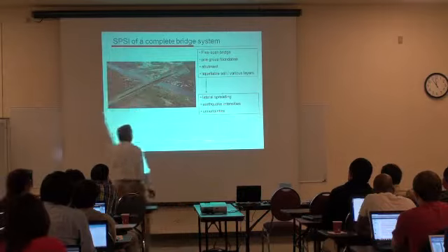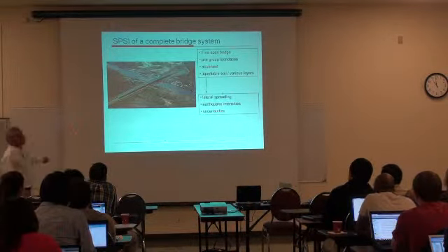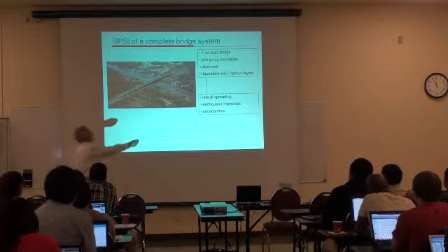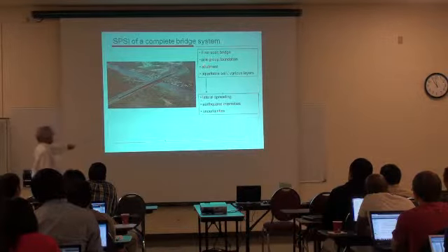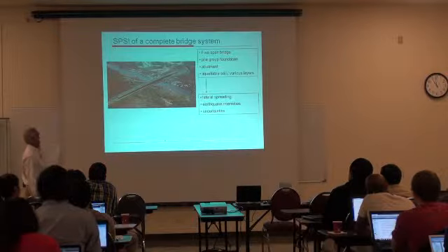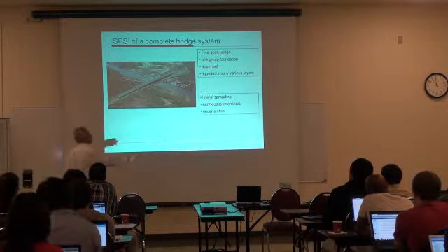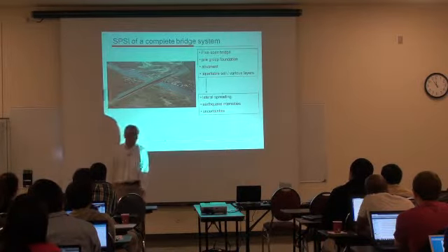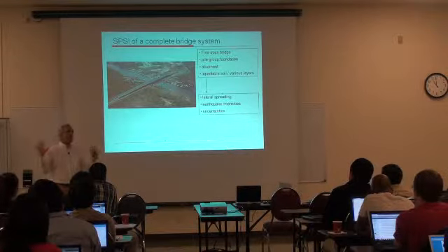This other example, I had to do a compromise. We wanted to model the whole bridge and the soil. So it was a 5-span bridge with a pile group foundation, with abutments, and with liquefiable soils with different thicknesses at different points. We wanted to consider lateral spreading. We wanted to consider different earthquake intensities. And we wanted to consider uncertainties. So you have a big problem here.